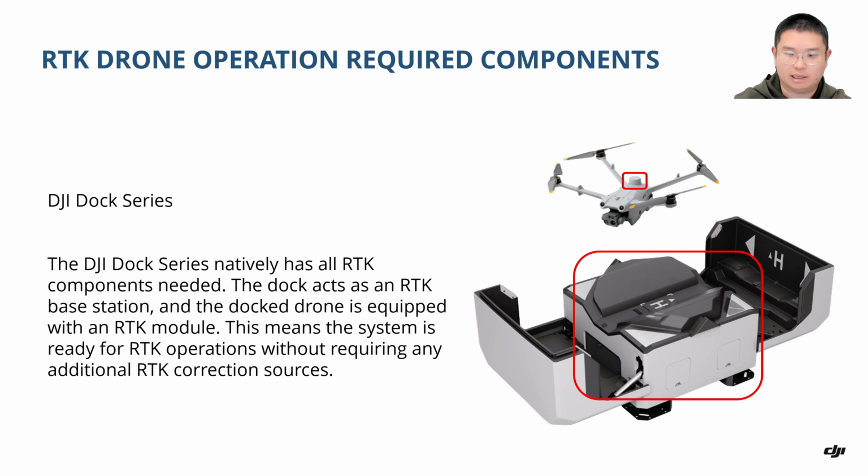And in some areas, you may have some reception, but the network is unstable. And as we all know now, RTK is happening in real time. When you have unstable internet, your RTK is unstable as well. This would result in inaccurate data.